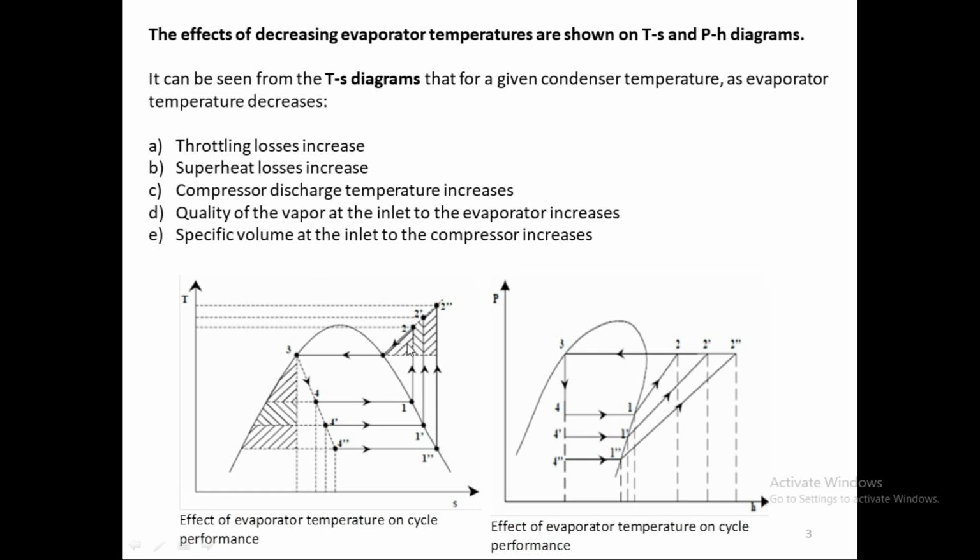The superheat loss increases on the compressor side. Before, at stage 1, it had to compress from here to point 2. But if we lower the evaporator pressure, now it has to go from a lower pressure to a much higher pressure, so to a much higher temperature. Then this heat has to be rejected to the environment before it comes to saturation, and we lose this much heat.